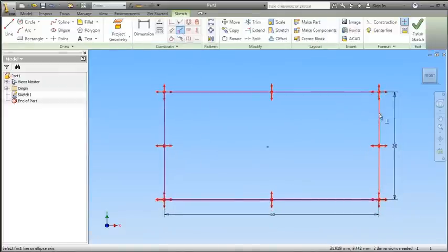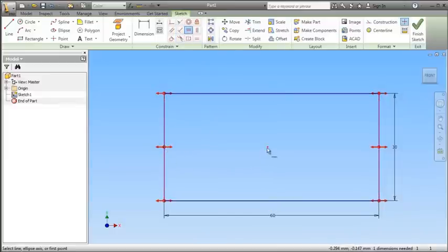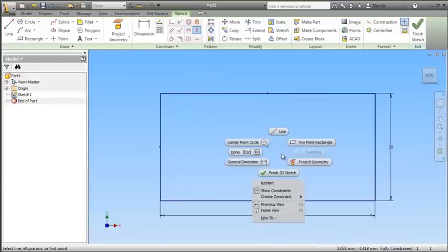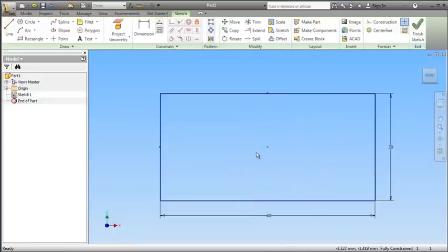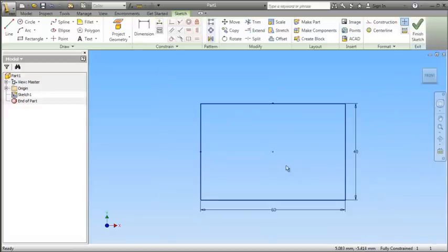For example, the angular degree of freedom on the line on the right. We can assign horizontal constraints between the center point of the sketch and the vertical edge, or vertical constraints between the horizontal line and the center of the sketch. That will effectively center this rectangle on the origin of the sketch. We can create equations or change the dimension values and update things.